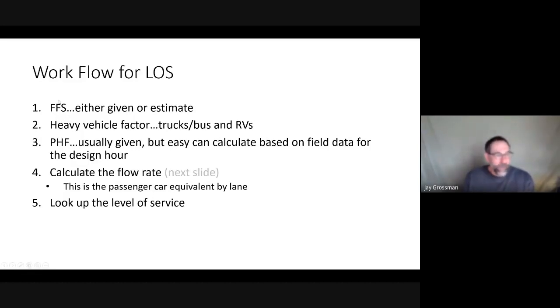So you're going to have an equation, or you're going to be told what the free flow speed is, right, through there. And you can calculate free flow speed. Remember, that's all that stuff about, well, if you don't have enough shoulder room or your lanes are narrower, and so forth and so on, that's where that comes into calculating your free flow speed.